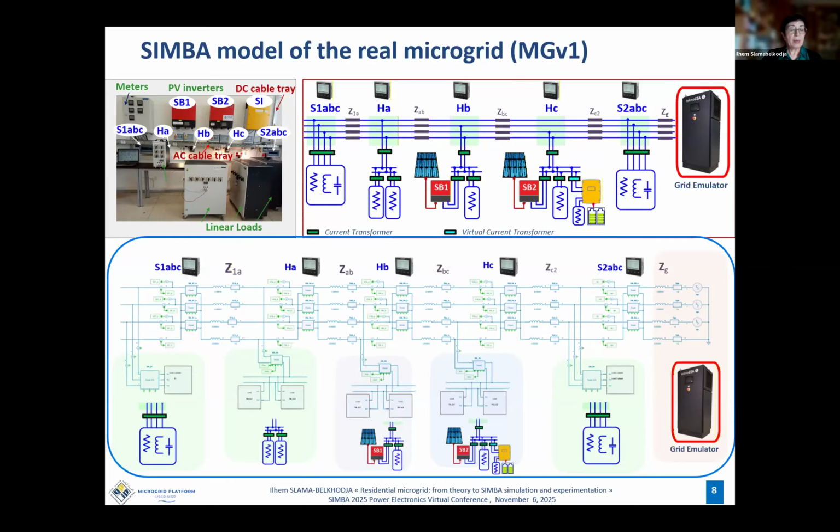PV systems are modeled as controlled current sources where the reference current is determined by a given input active power. The reactive power is null. Also, at first, line impedances are set the same, with a common value. A three-phase power analyzer is set at each connection point.